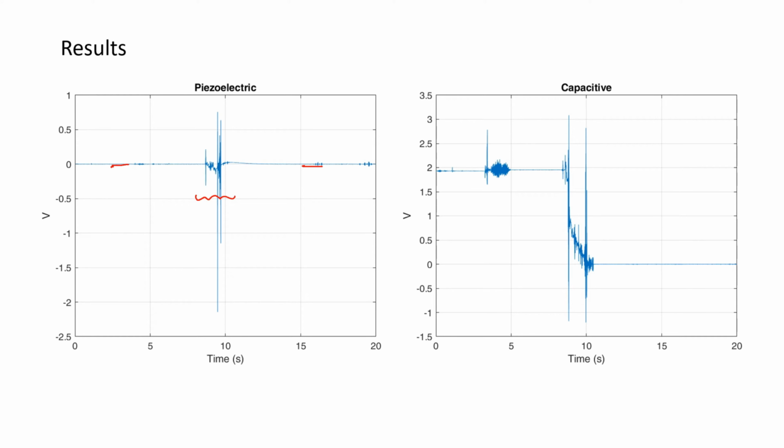With the capacitive accelerometer, we were in one state when we started, and we ended at another state. This is simply because we're going from plus 1G to minus 1G. And we can calculate the delta voltage, the change in voltage between the two. We are getting a voltage measurement of 1.94. Dividing this by 2G will give us the sensitivity value for the capacitive accelerometer.